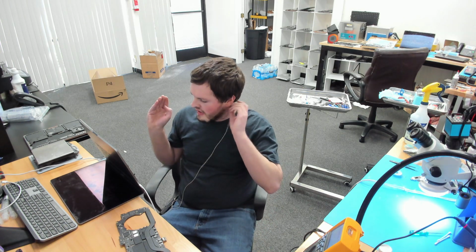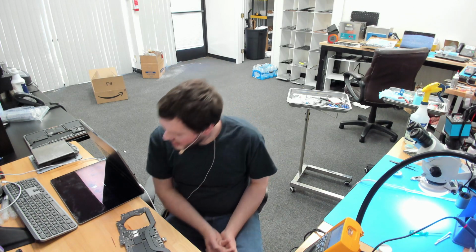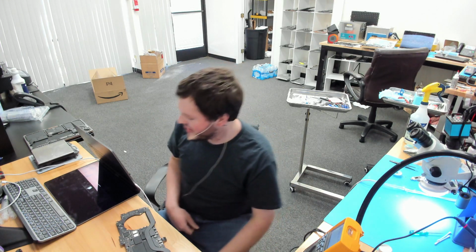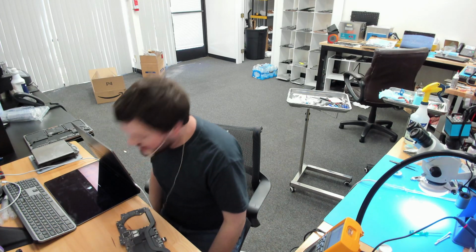Diagnostics and figuring out how stuff happens is a very fun part of this job, because the user did go to the Apple Store first. They replaced the top case and the battery, and then they said it had a logic board issue. My guess is they did try a DFU restore. It did not work because half of our NANDs weren't working, and it failed, which forced it into recovery mode. Anytime you see a device in recovery mode, it typically means a DFU restore was interrupted or failed in some way. And in this case, it does have an Apple logo, but we're going to wait until this is fully booted and then go from there.